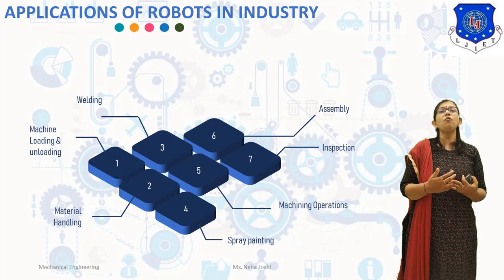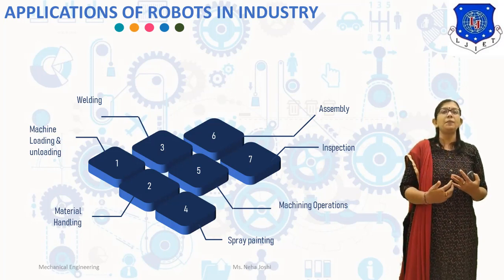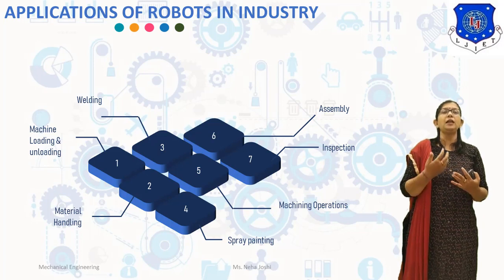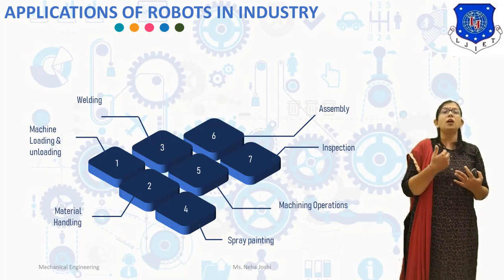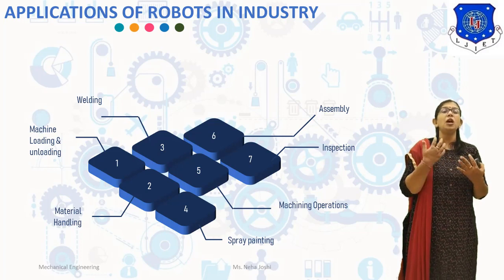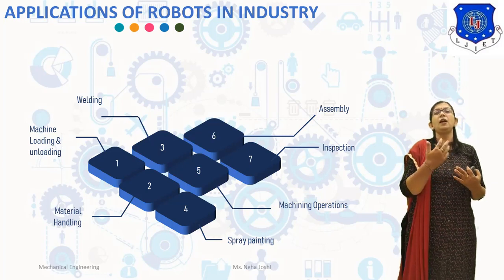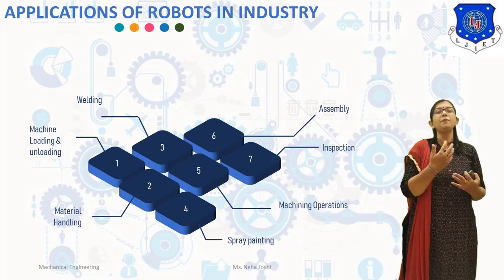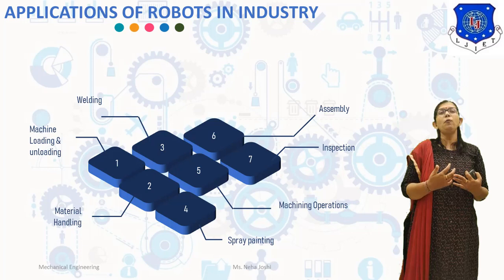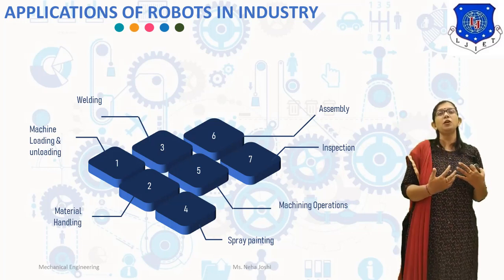The assembly normally involves following operations: mechanical fastening, soldering and brazing, welding, press fitting, adhesive bonding. The assembly involves highly repetitive and boring operations which lead to human fatigue. This may adversely affect the product quality and productivity. The use of robots in assembly results in reduction in manufacturing cost and improves the productivity.